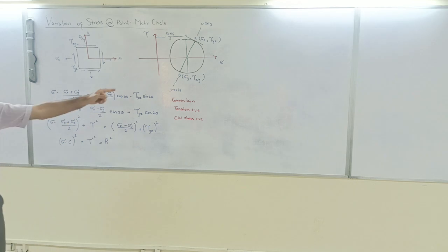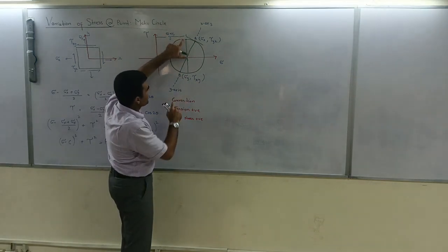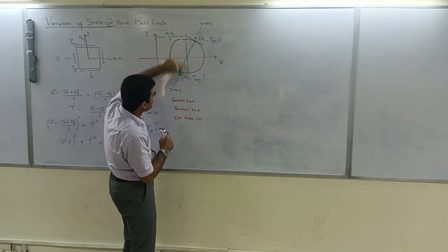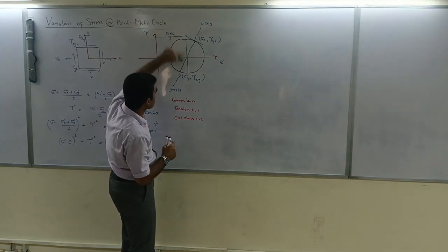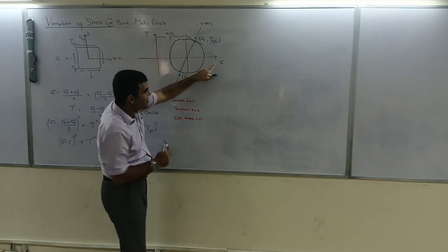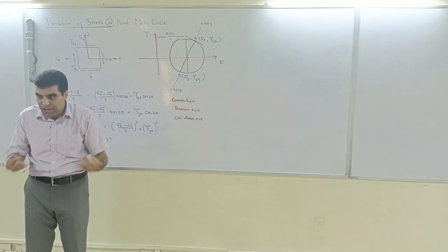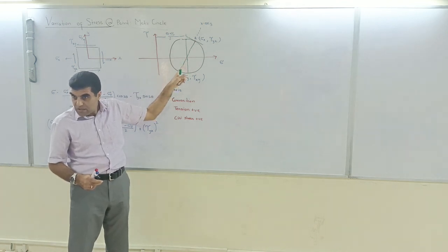In this scenario, if you draw this axis which is vertical, you can see there is a shear stress which is this one, but there is axial stress also, and the axial stresses both are positive, that means tension, and both are equal. Can you see that?